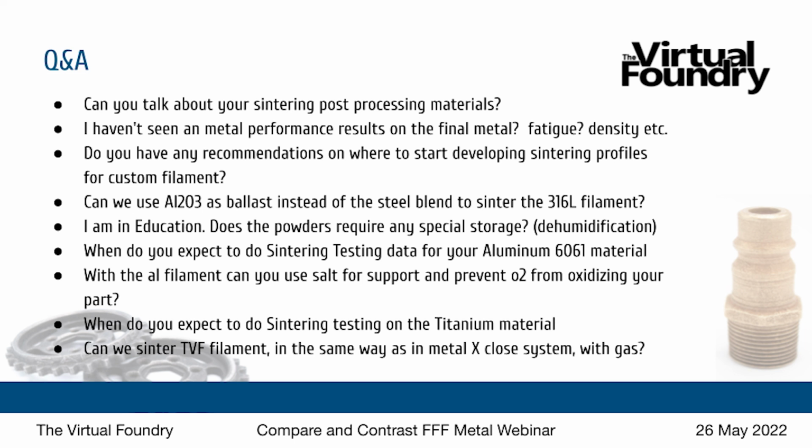But the application that we're working on is biomedical, so the specs are very stringent. It has to be absolute perfection. At this point, we're getting good titanium parts, but they have too much oxygen in them and too much carbon. As we figure out how to mitigate those two properties, it'll come into the mainstream, and hopefully by the time we're done, we'll have a sintering house that we can refer people to have them sinter their titanium parts.